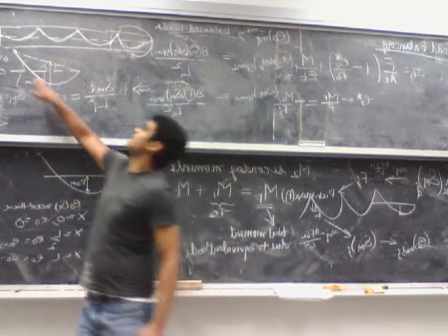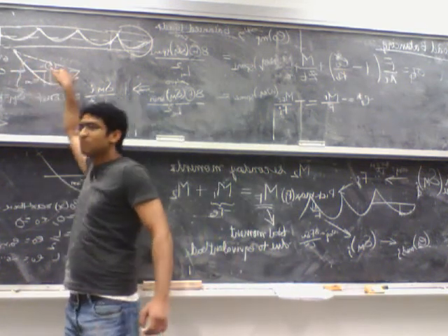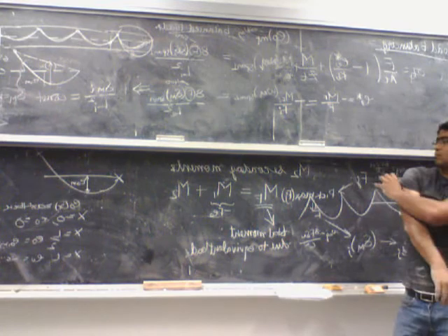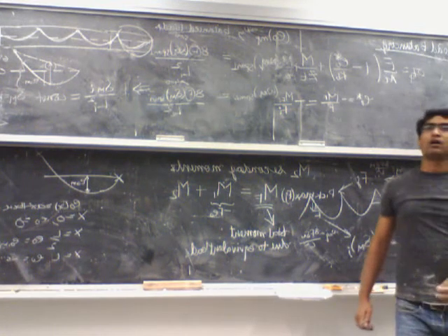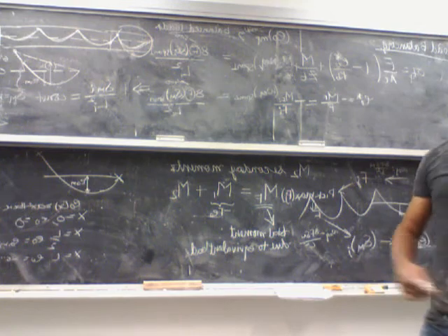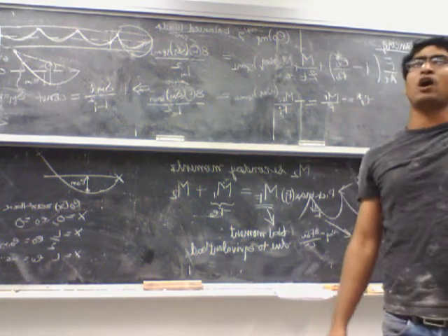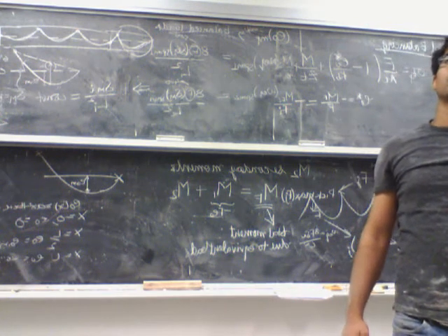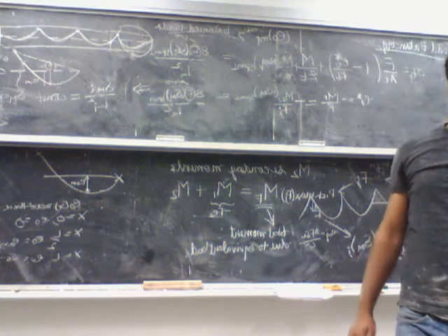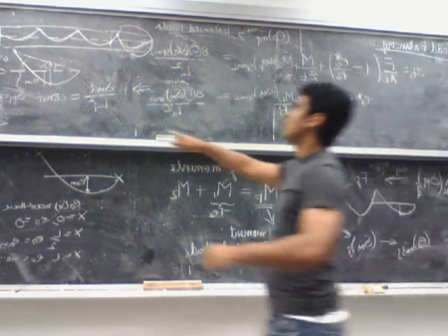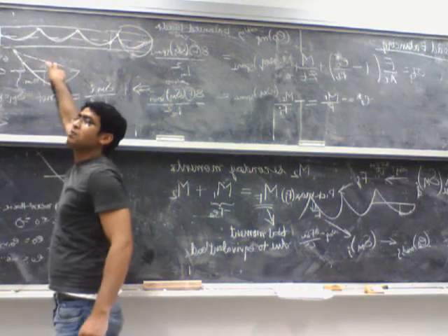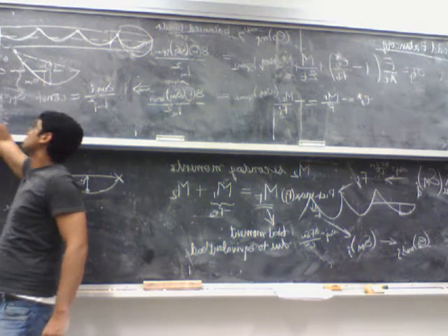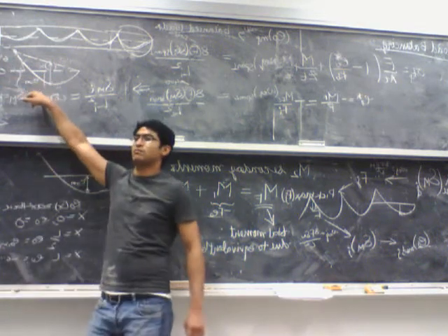I can actually lower this and make sure that I get a different tendon profile. Even if we don't tell you, you can always fix it at the support at the maximum. It doesn't actually limit you, because the higher this value is, the larger my delta M is. It doesn't matter whether you are in the end span or the mid span. So you maximize one and then you try to find out the other one.